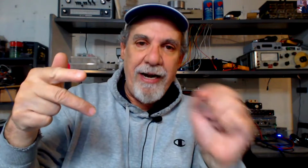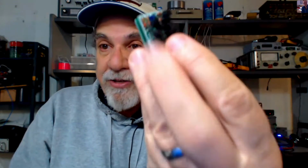Now, again, that's all it has to do. If it follows that equation, generally, if it has the two different inputs and an output, it's an op-amp, whether it's one of these, whether it's a discrete transistor module, like one of these, or even a vacuum tube module. It doesn't matter what the devices are, what the packaging is. An operational amplifier is defined specifically by having two inputs, one output, and the output is proportional to the difference between the two inputs. Now, if you've got that, you've got an op-amp.